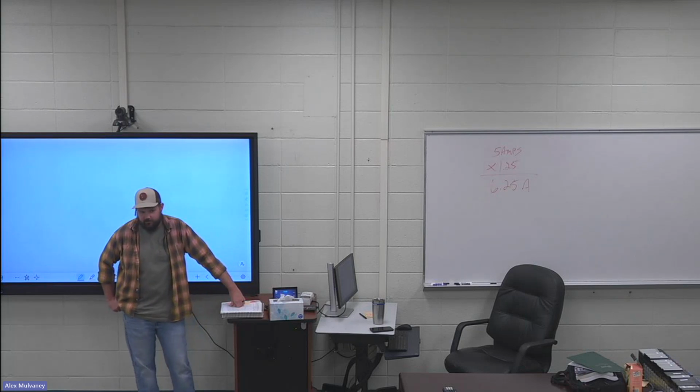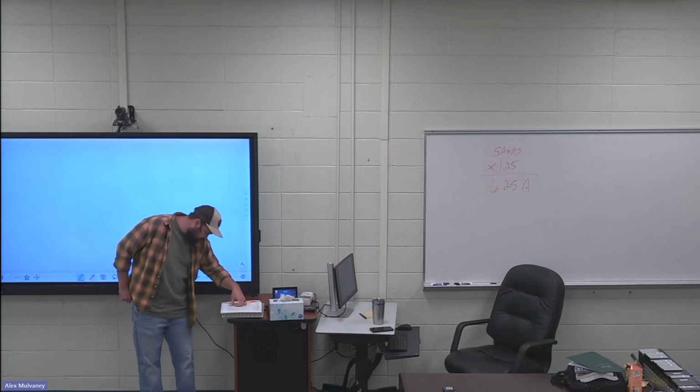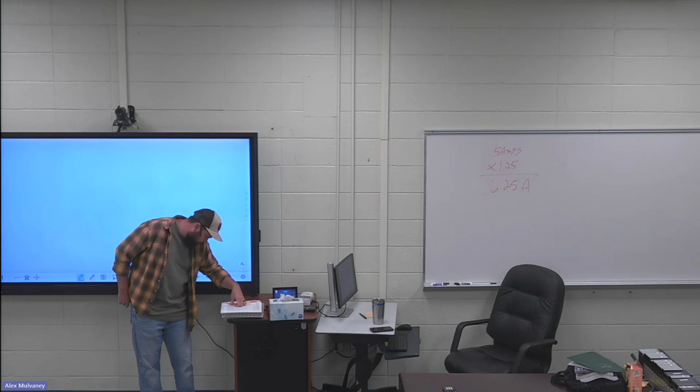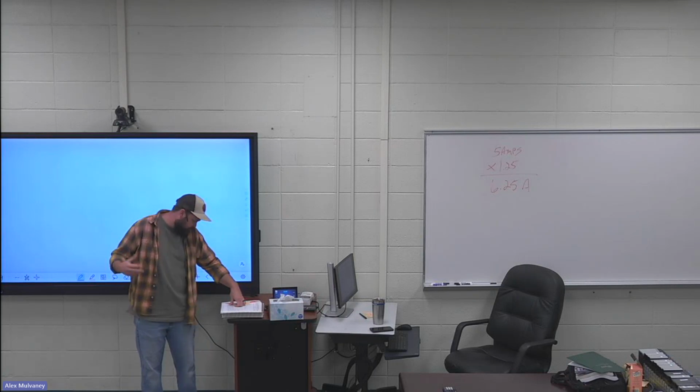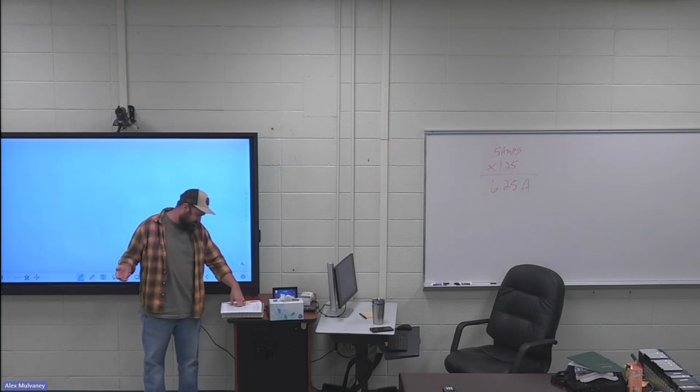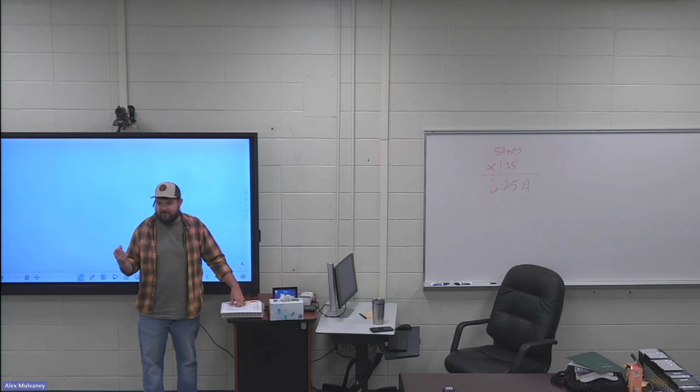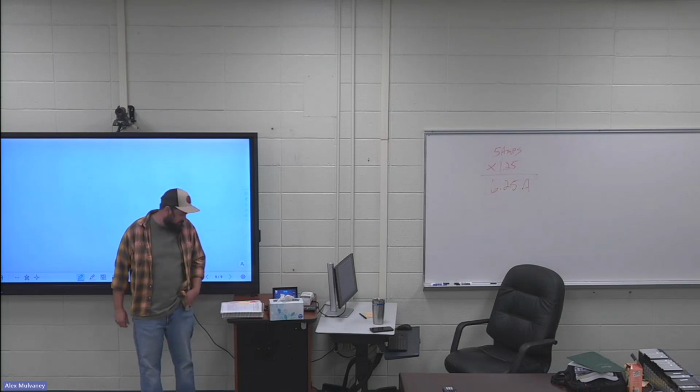So what does that note allow us to do? It says since we have one load for a counter-mounted cooking unit and less than 2 wall-mounted units, I can combine those nameplate ratings and treat it as one. That's what that note on that code is allowing us to do.